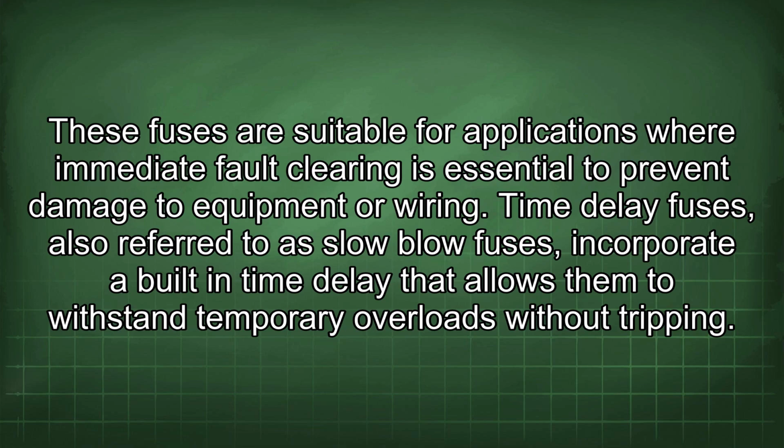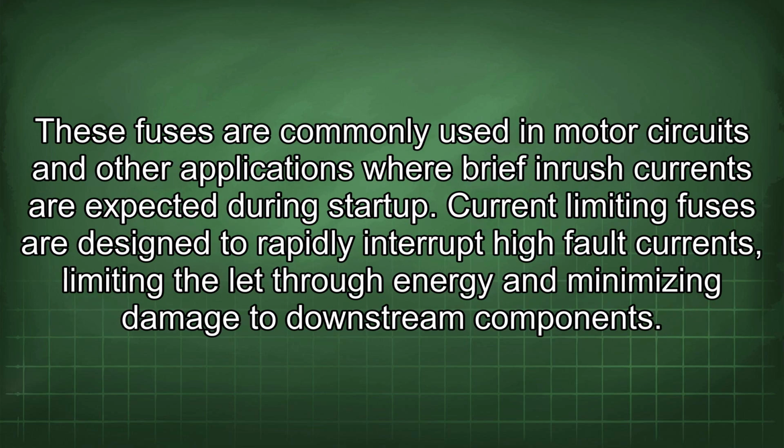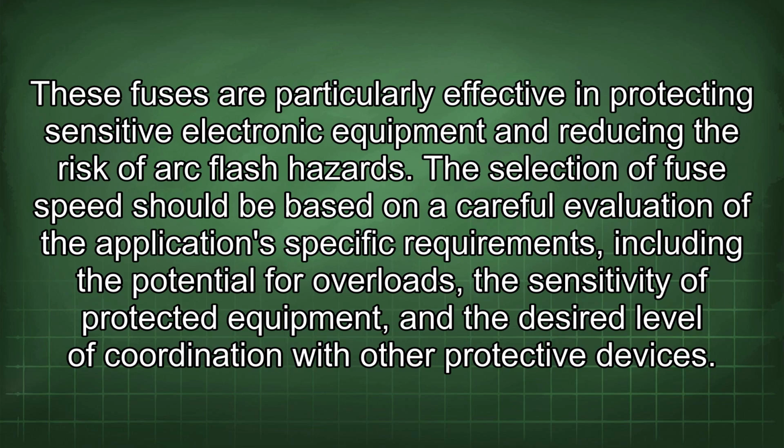These fuses are suitable for applications where immediate fault clearing is essential to prevent damage to equipment or wiring. Time delay fuses, also referred to as slow-blow fuses, incorporate a built-in time delay that allows them to withstand temporary overloads without tripping. These fuses are commonly used in motor circuits and other applications where brief inrush currents are expected during startup. Current-limiting fuses are designed to rapidly interrupt high fault currents, limiting the let-through energy and minimizing damage to downstream components. These fuses are particularly effective in protecting sensitive electronic equipment and reducing the risk of arc flash hazards.